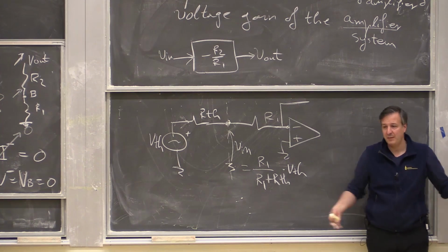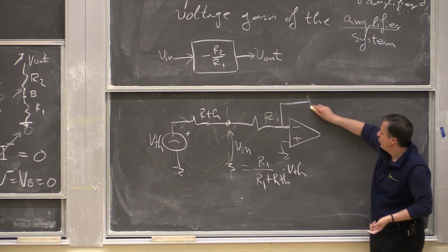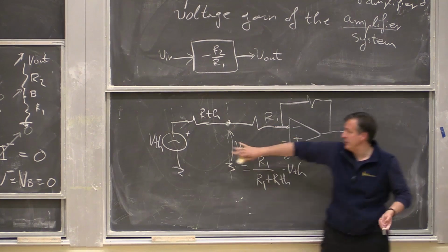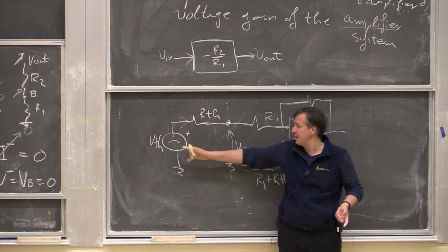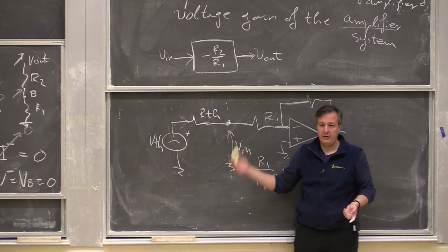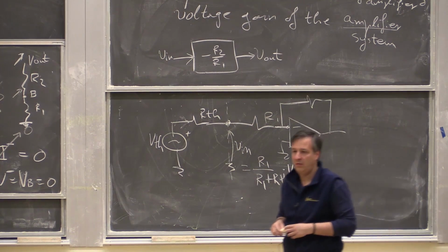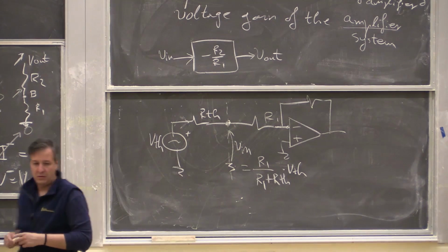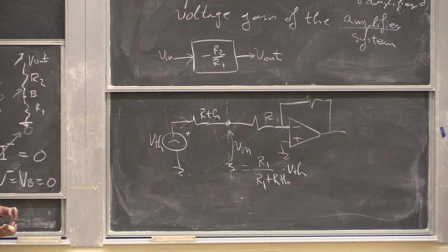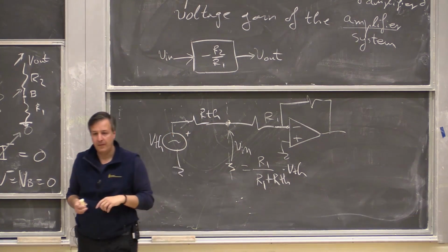So this whole composability now breaks. I just wanted to be able to add this circuit without disturbing this circuit. By disturbing I mean that V Thevenin would all show up here, and there would be no current flowing. Right? So what circuit do we know that we can add here to save the day? I want to isolate this V Thevenin, R Thevenin from the inverting amplifier without changing any total calculation. Right? Just want to put something here that creates a 0 current here, but replicates the voltage.